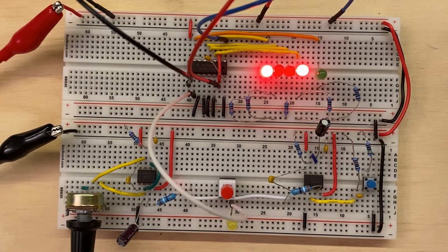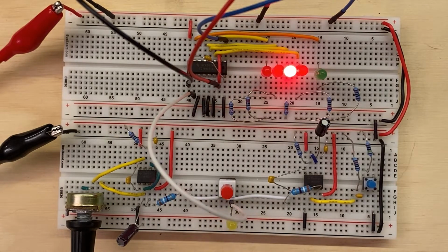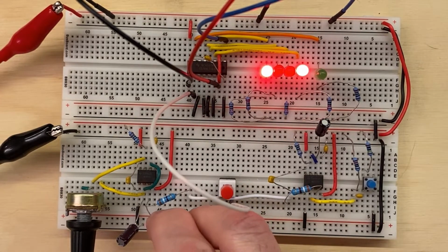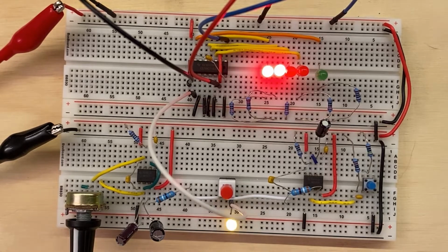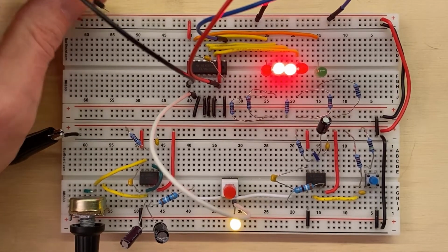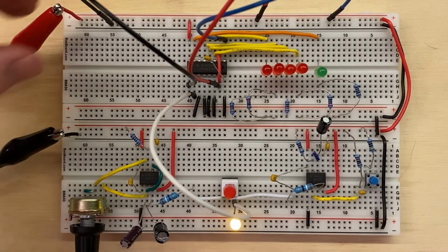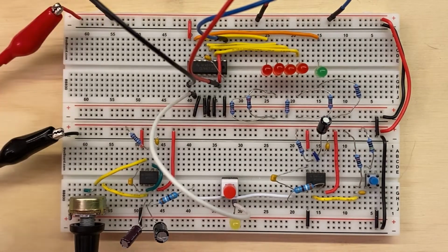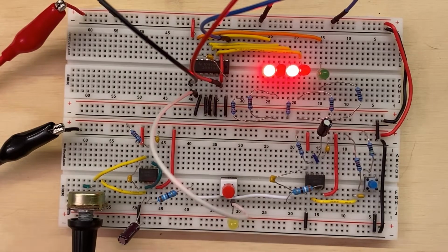So let's look at the load pin. Actually, before I do that, I want to add a big fat cap on our clock. So this is going to slow our counter right down. And basically, this is just going to demonstrate that the moment this lights up, you see it change. So it really is right on that rising edge. And let's take that master reset. I could reset it right now, but it's only going to happen on the rising edge. Doesn't go to 0. And so it's just important to note that it's the rising edge of the clock that's what counts. So we could go back to normal mode, take out that fat cap.